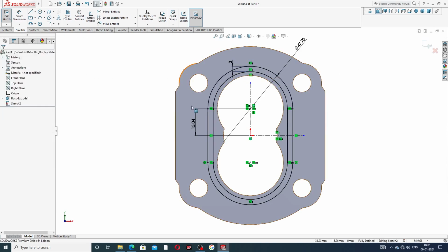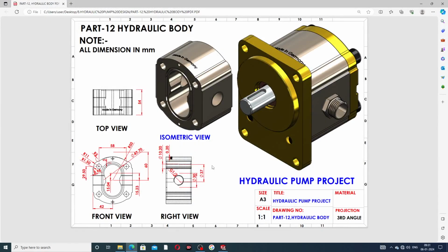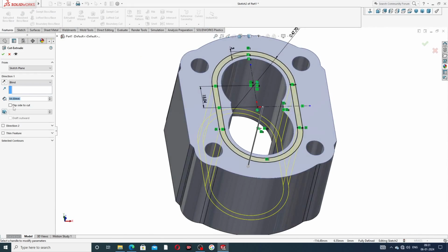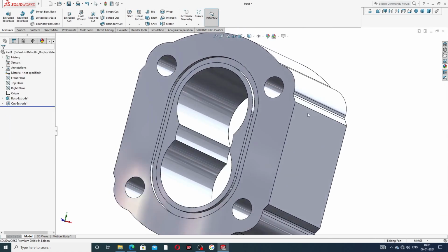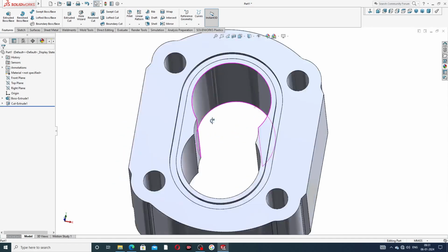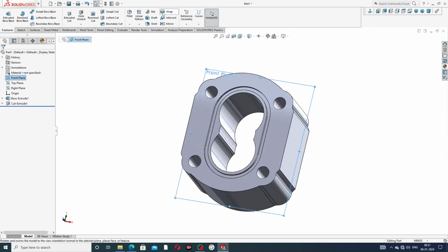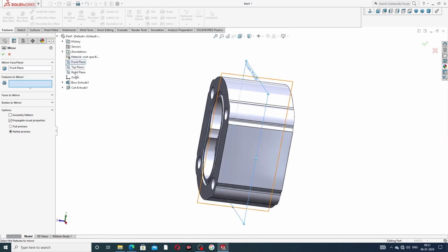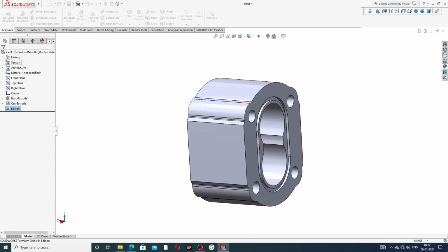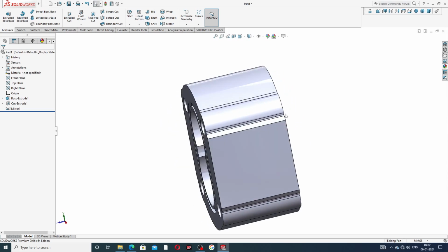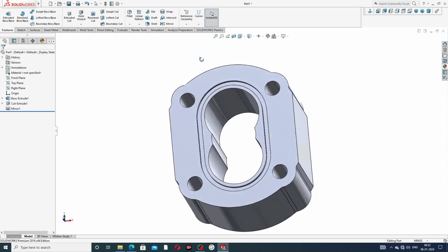And this offset is used here, and the cutout is only 2 millimeter, not mentioned here, but this is 2 millimeter cut out, using extrude cut. Extrude cut is only 2 millimeter because this uses a rubber belt. Click OK. This uses a rubber washer, very nice looking. Also use the front plane because this uses a mirror, select this and cutout, and click OK. The back side is also correct, and both sides use a rubber washer, and this is perfect.